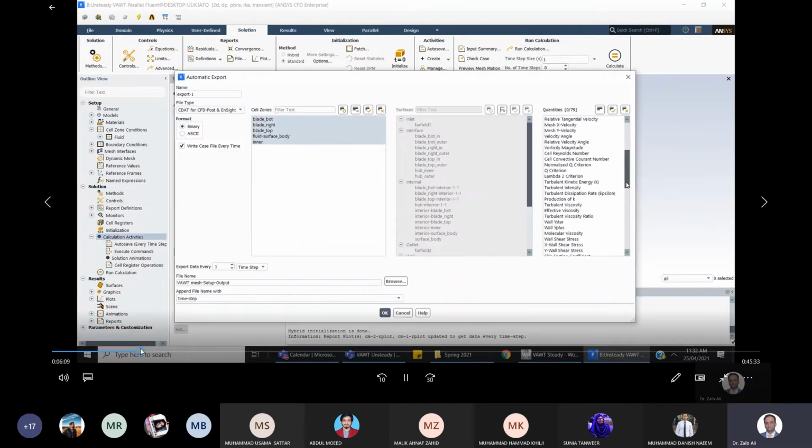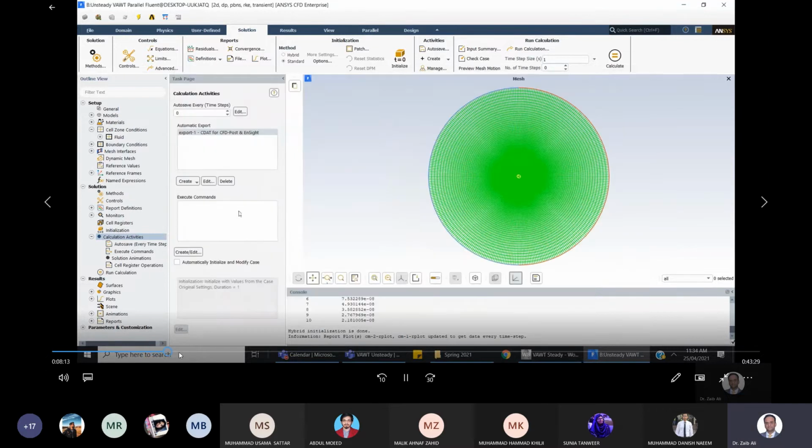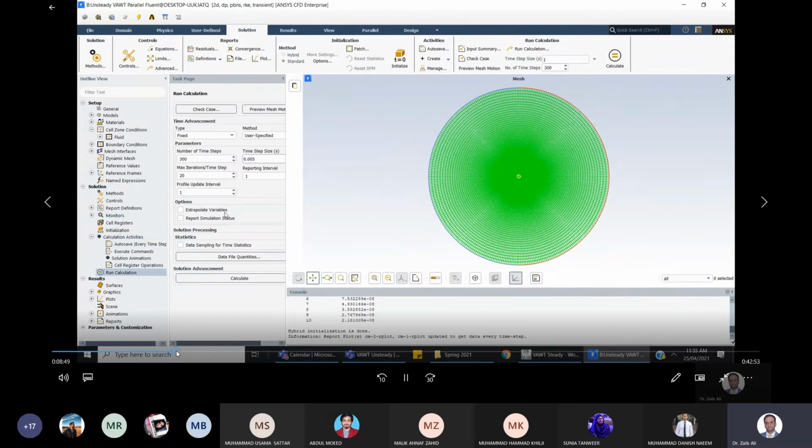Okay, somewhere here there is an option where, as I mentioned, you can also create the animation of the unsteady flow in Fluent itself. I've just clicked some tabs over which you can follow. Otherwise, a good option is always to go for CFD-Post and do the post-processing there. So these are all the steps mentioned for how to save data for later post-processing.